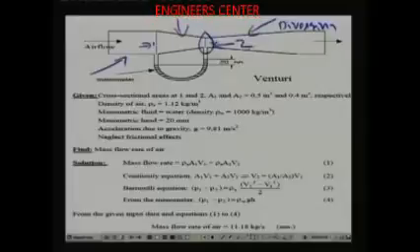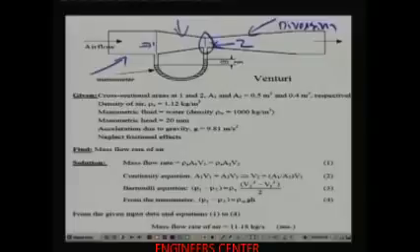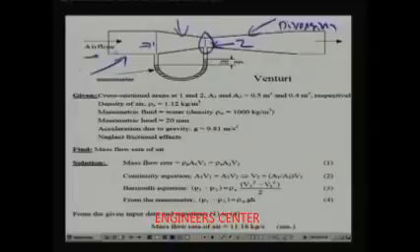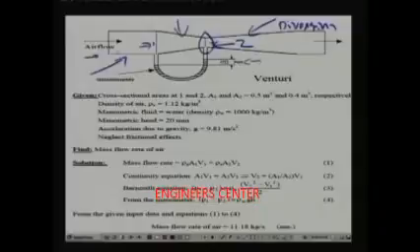is 0.2. And the venturi has a manometer here, and one end of the manometer is connected to the inlet to the converging section, that means 0.1, and the other end of the manometer is connected to the throat portion, that means 0.2, and this manometer is filled with some manometric liquid. So, basically the air flows through the venturi, and because of the air flow there will be some pressure difference in the manometer, that means there will be a manometric head here, and from the characteristics of the venturi and by measuring the manometric head you can calculate the air flow by applying Bernoulli's equation.